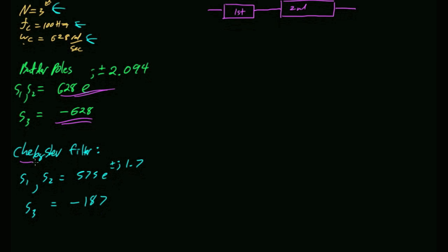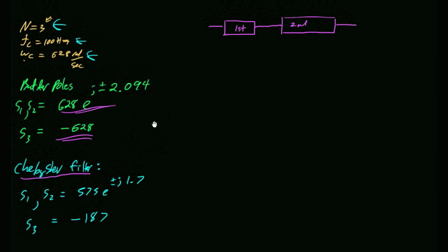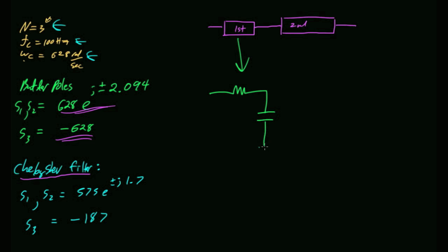Now, and just to start things off easy, let's just start with the first order. Okay. So how do I build a first-order low-pass filter? RC circuit, right? Even I know that. Okay? So my first order circuit is going to be an RC circuit. How can I select my values for R and C? What's my criteria?